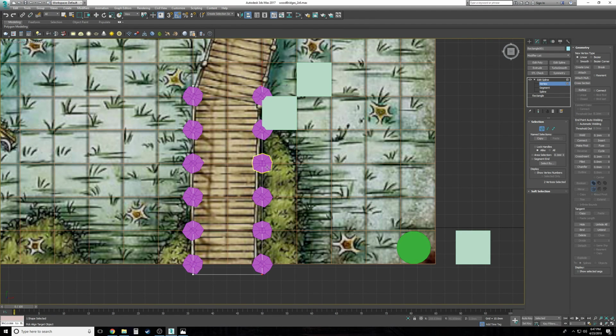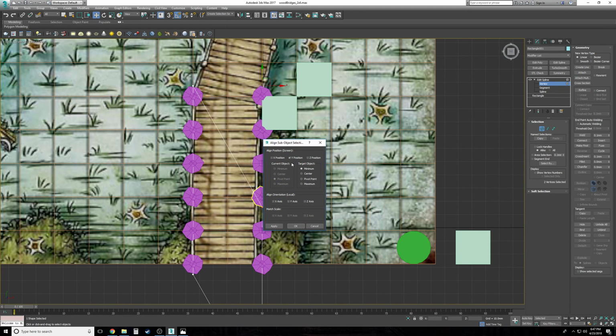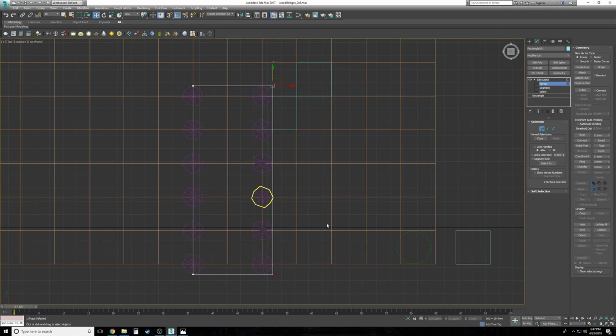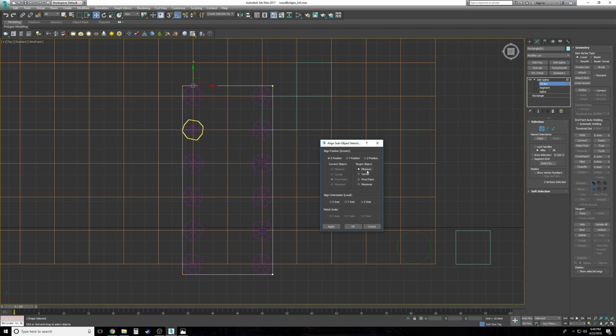We're going to switch over from the Y. Select any of these pieces on the right, clear your Y, because we're going to the right now, which is X. Just like this red leg says a little X right there. And we want maximum because we want it all the way to the right. So it stops at that point. See how it's on the outside now? Do the same thing. And we're going to go on any of these and then make it minimum now because we're going to the left.